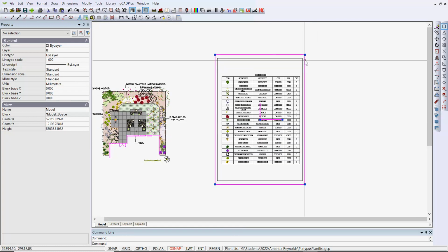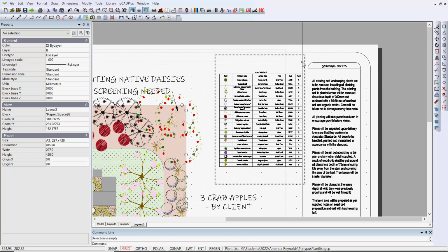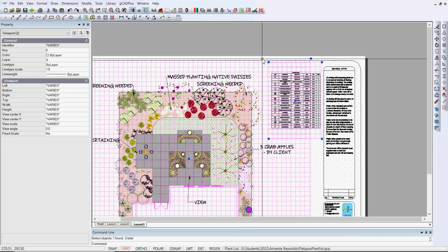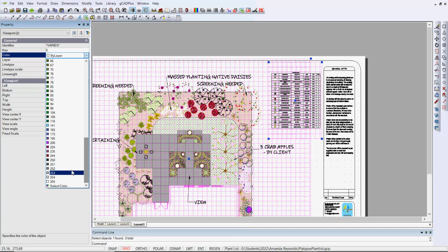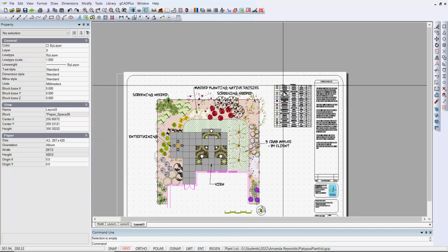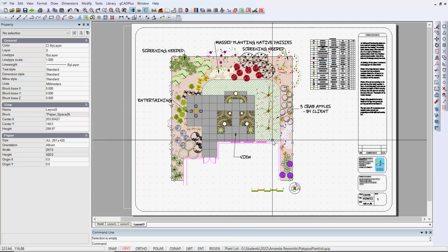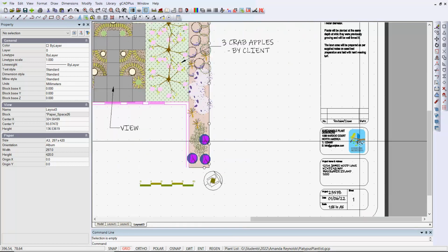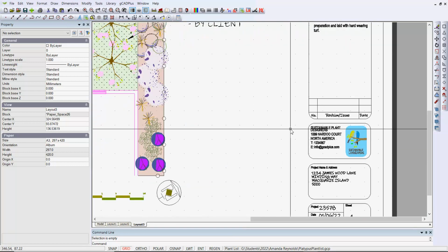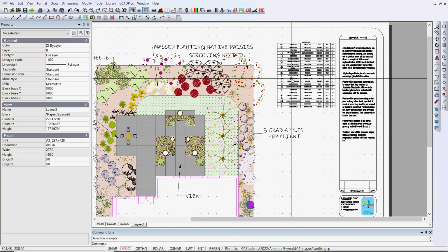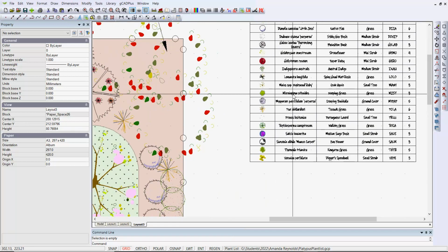When you go to Layout Space, what I've done here is create a new floating viewport, this one here, and if we dive in and change things, we can zoom in a little tighter and display it on the page. What I'm going to do is pick the floating viewports and make the color of those white, so the borders of those floating viewports won't show. So now if we zoom extents, this is an A3 sheet, and we're starting to input some data.